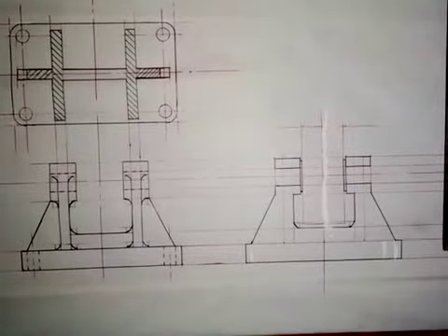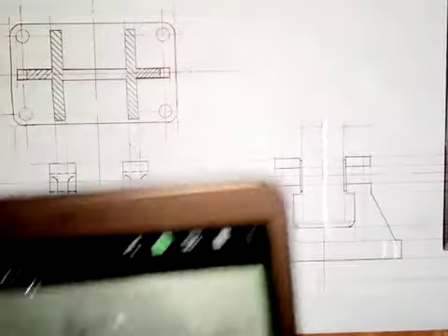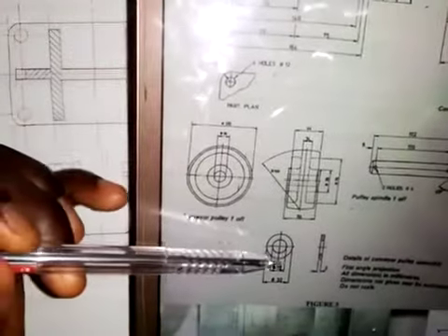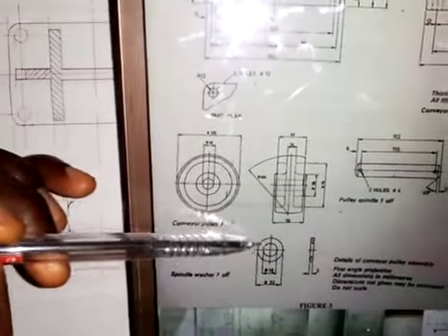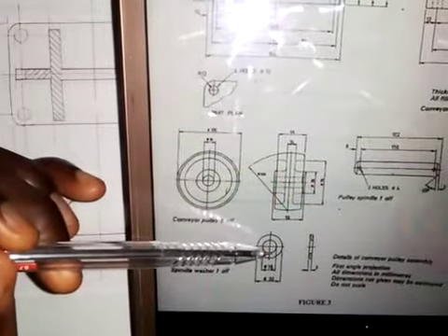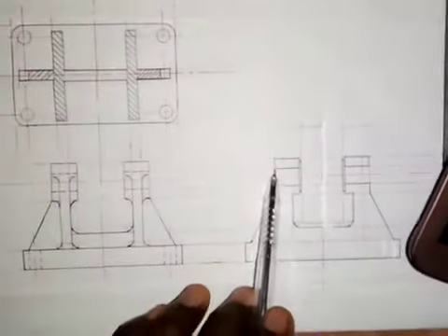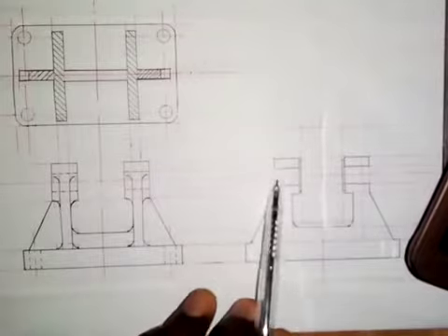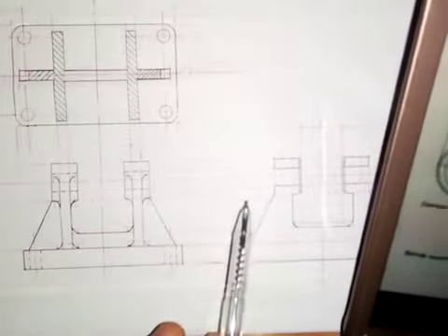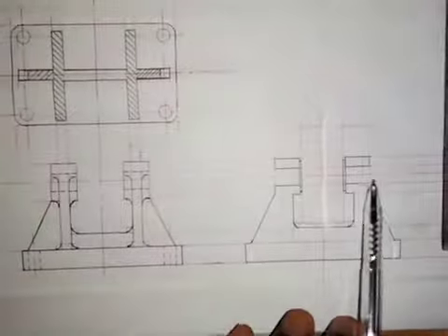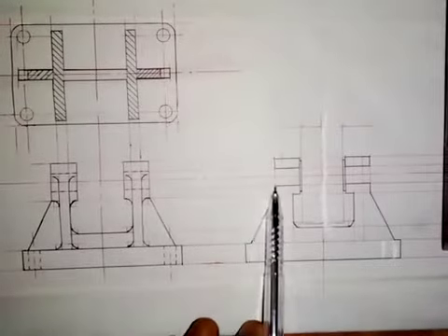And then let's put the spindle, the pulley spindle there. So this is the pulley spindle. The diameter is 18 as it is entering this hole in the washer. The diameter of this small hole in the washer is 18 millimeters, so it will enter. From here to here is also 18. So this is 18 millimeters for this hole. The spindle pulley is entering here, so this is 18 from here to here.